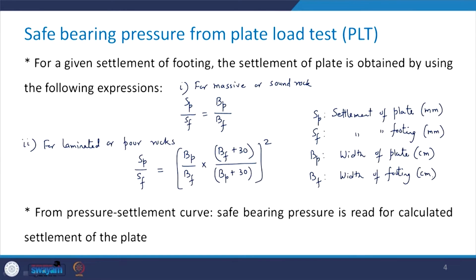So, from the pressure versus settlement curve, you can obtain the safe bearing pressure for this calculated settlement of the plate.